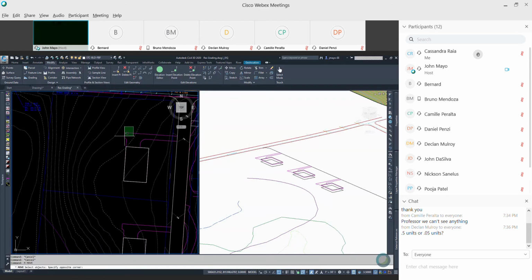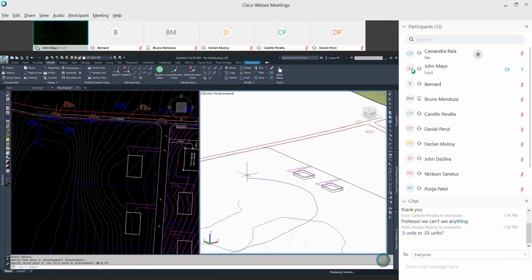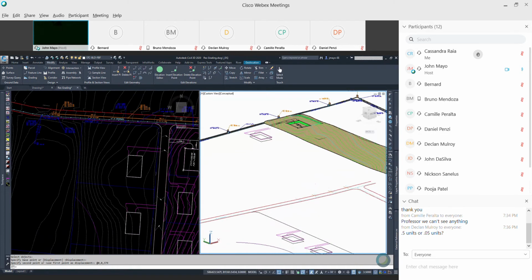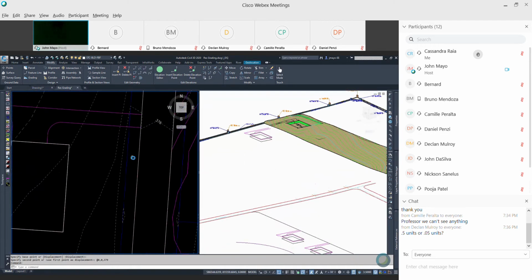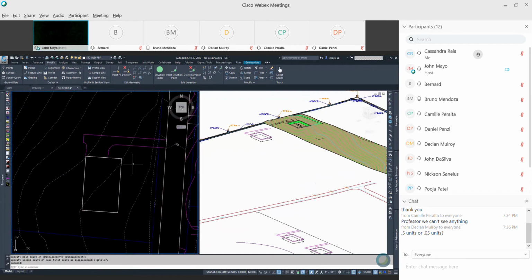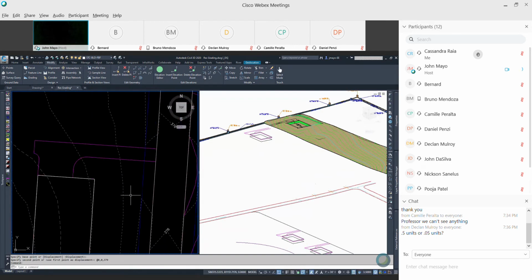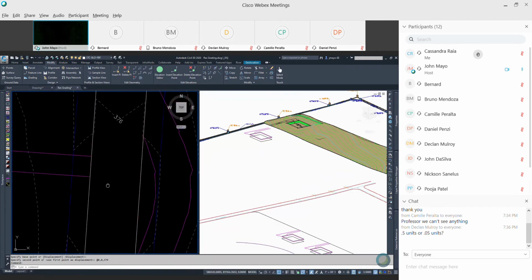Notice I was watching in my 3D view, and I noticed that only 2 of the polylines moved. So I undid that all because they weren't all selected. I go at 0, 0, 379, and they all came up to the elevation I want them at, or at least begin at. All right, so I could do the same down here and prepare these polylines.